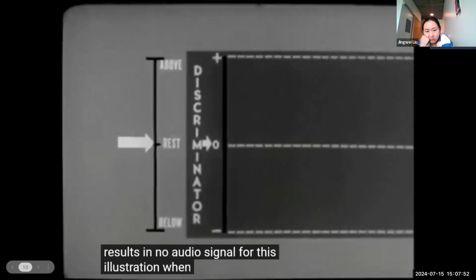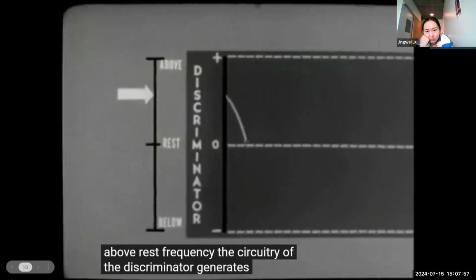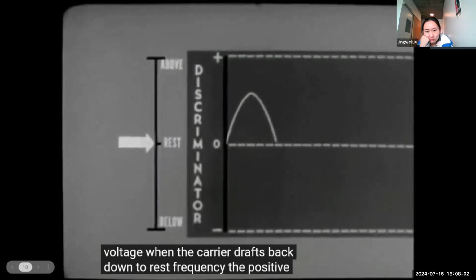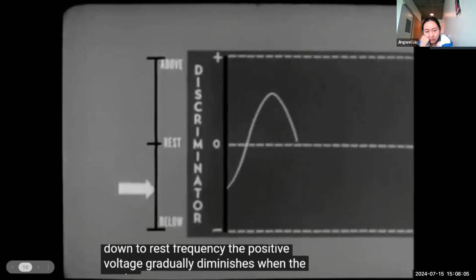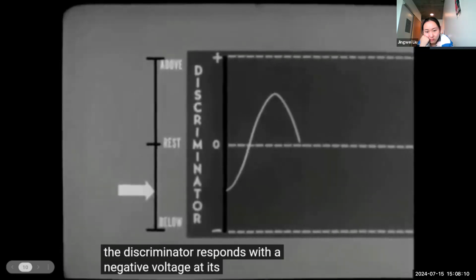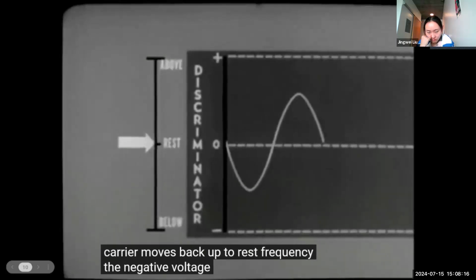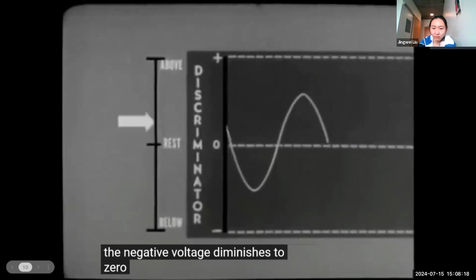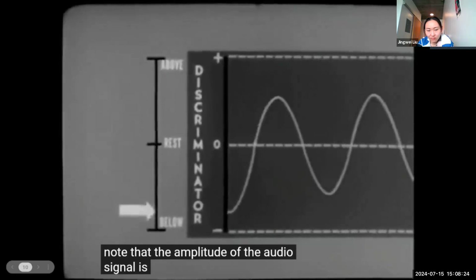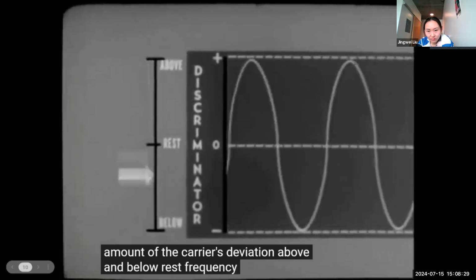For this illustration, when the carrier deviates above rest frequency, the circuitry of the discriminator generates a positive voltage. When the carrier drops back down to rest frequency, the positive voltage gradually diminishes. When the carrier deviates below rest frequency, the discriminator responds with a negative voltage at its output. When the carrier moves back up to rest frequency, the negative voltage diminishes to 0. Now watch the continuous action. Note that the amplitude of the audio signal is an accurate reflection of the amount of the carrier's deviation above and below rest frequency.